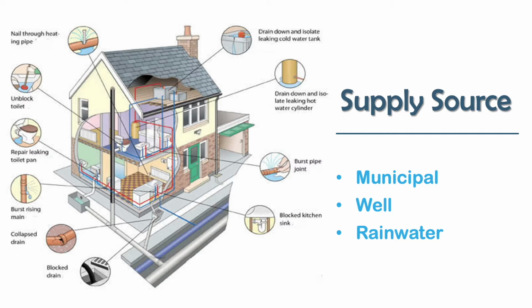Your water supply for a well is going to vary with the amount of rainfall and the usage that you have. Most places, certainly in the state of Oregon, require you to have the ability to have 5 gallons per minute come from a well. And wells do require regular testing.